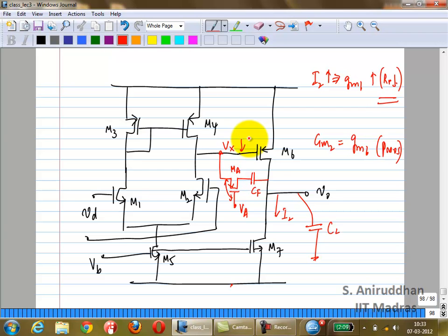Increases. What happens to Vx? You are basically having the same transistor, you are increasing the current. The gate source voltage also has to increase, right? In this case, source gate voltage has to increase, in which case the overdrive VGS for MA decreases, if I had connected it to ground, if VA was ground. So definitely connecting it to ground is not the way.